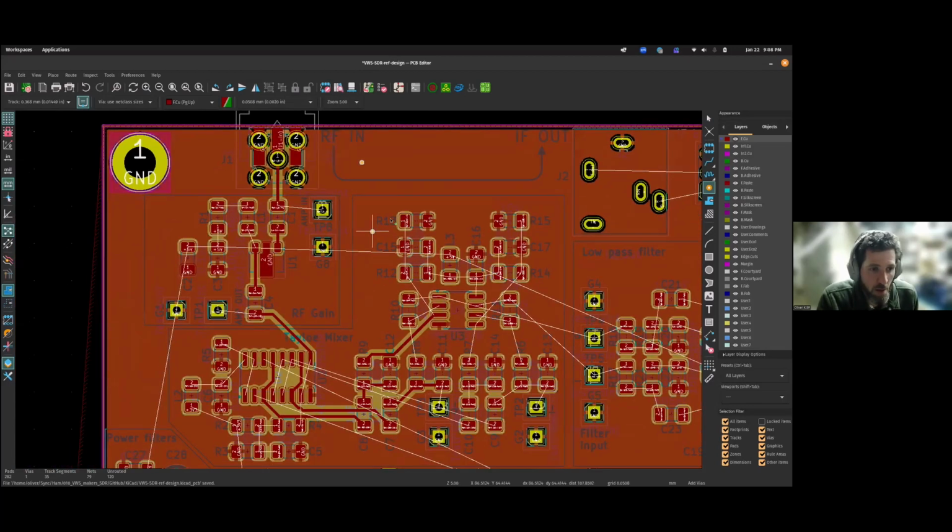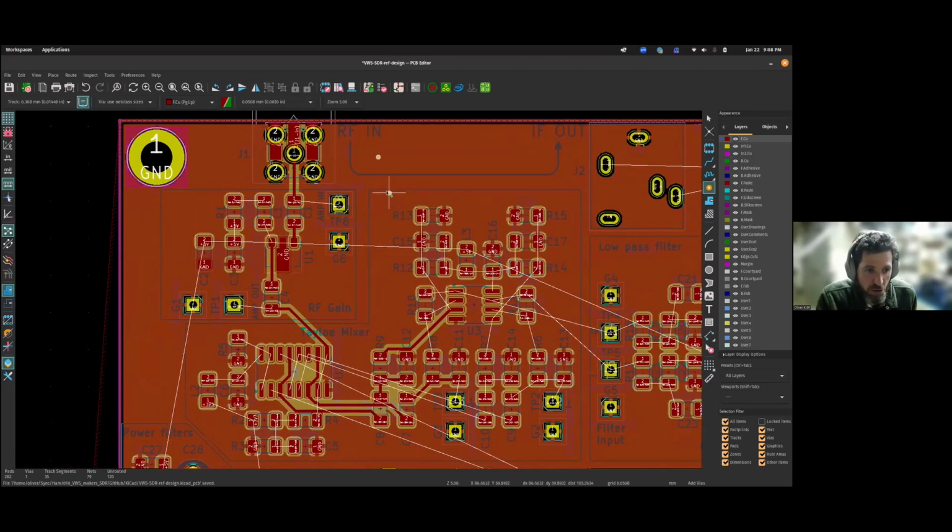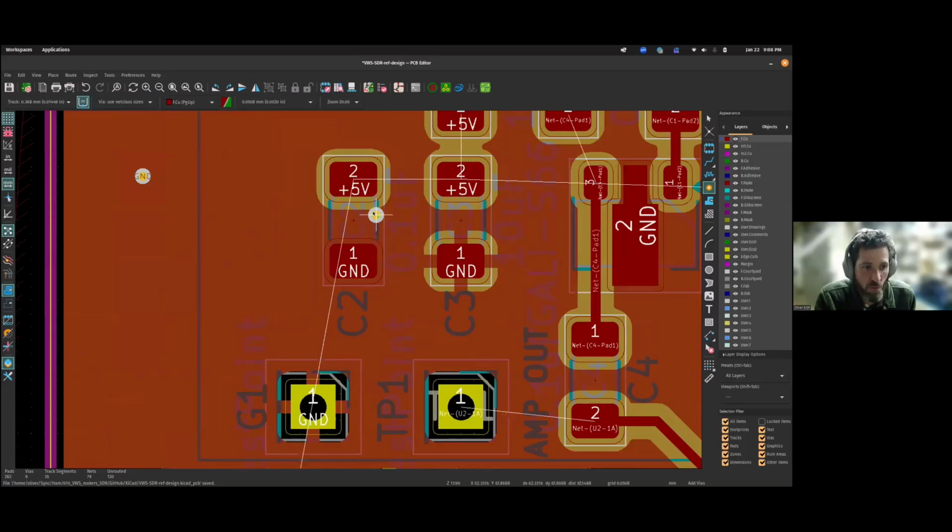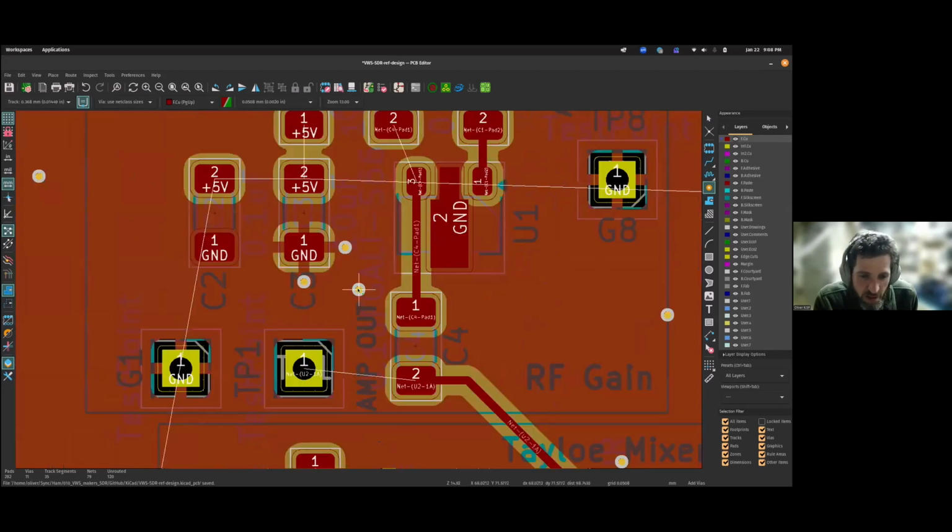So you should go around and put many vias on your board so that the ground lines are all connected together. Careful you don't click on a trace and accidentally ground a trace. It's good practice for components connected to ground to put at least one via close to the ground side so they have a nice electrically short connection to your ground planes. It matters a lot more at RF frequencies than at HF, but it's still a good practice to have.